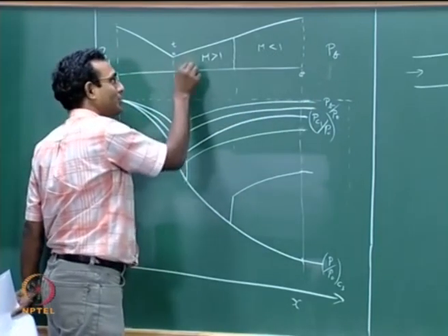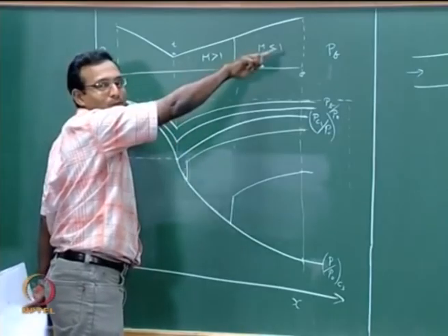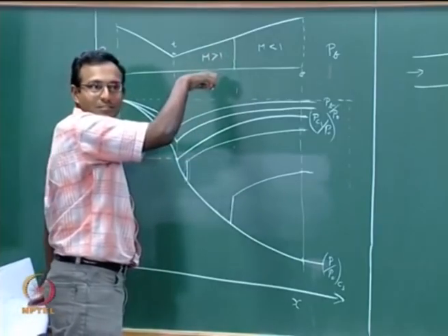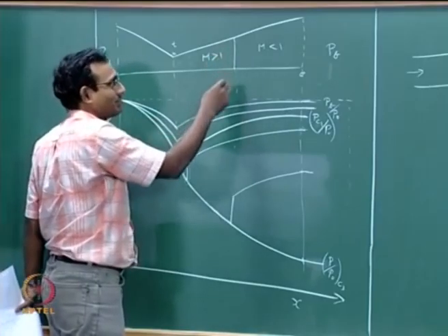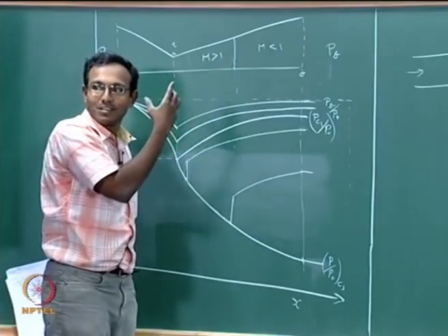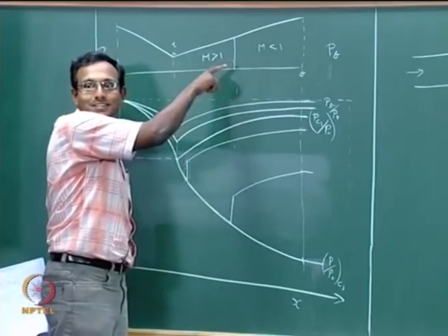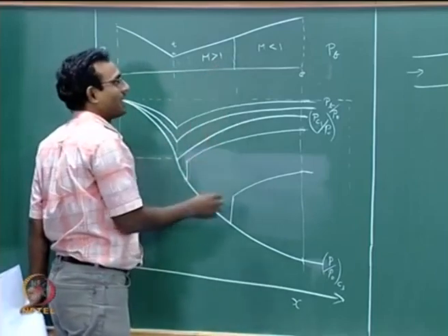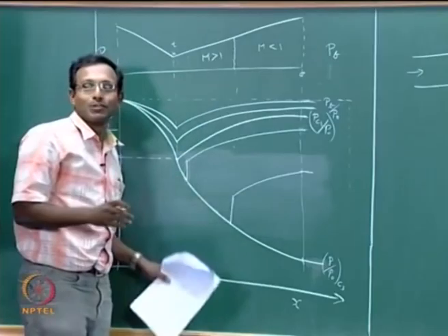So I decreased the pressure downstream, so there is an expansion wave coming in and weakening the shock which was originally here, and because of that the shock is being pushed by the flow more downstream. But as it goes more downstream, the Mach number changes, and because of that the shock finds a nice place to sit. It goes there, the shock becomes stronger and stronger. When the Mach number of the shock gets higher, it can run faster. But remember, the flow is also getting faster. It will go and sit at a new point where they are equal. Okay. That is where it sits. If I decrease too much, the shock will go further out.